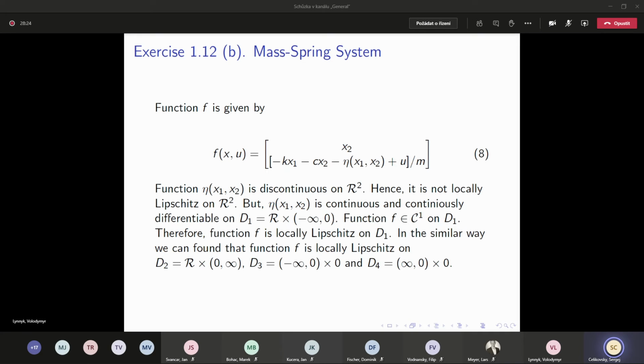This is an example where you have some mass lying on some surface and you are pulling it using some spring, and you can imagine that there may be strange behavior: you are pulling the spring and nothing happens, and then with a certain force suddenly the mass moves because it overcomes dry friction. Meanwhile the spring is stretched, so the mass moves, but then it moves quicker than you are stretching the spring.